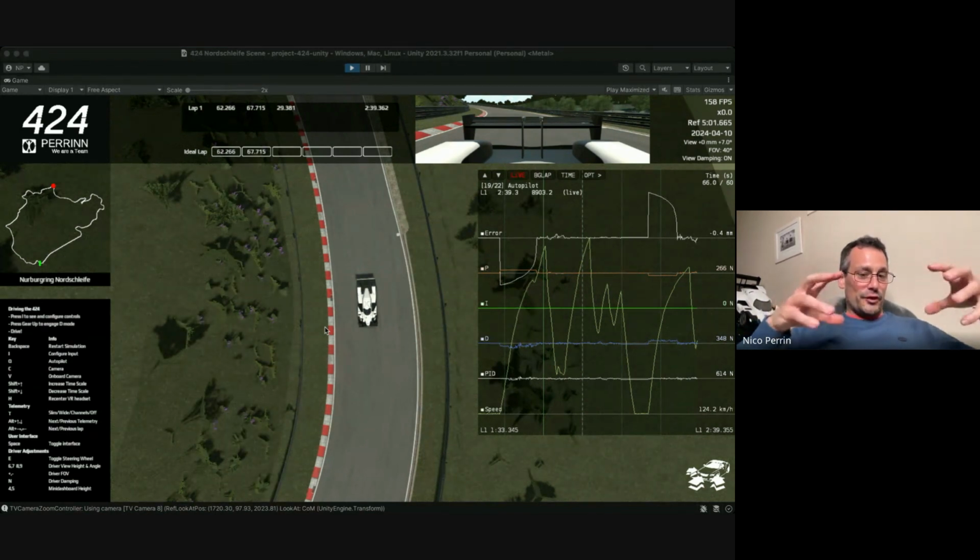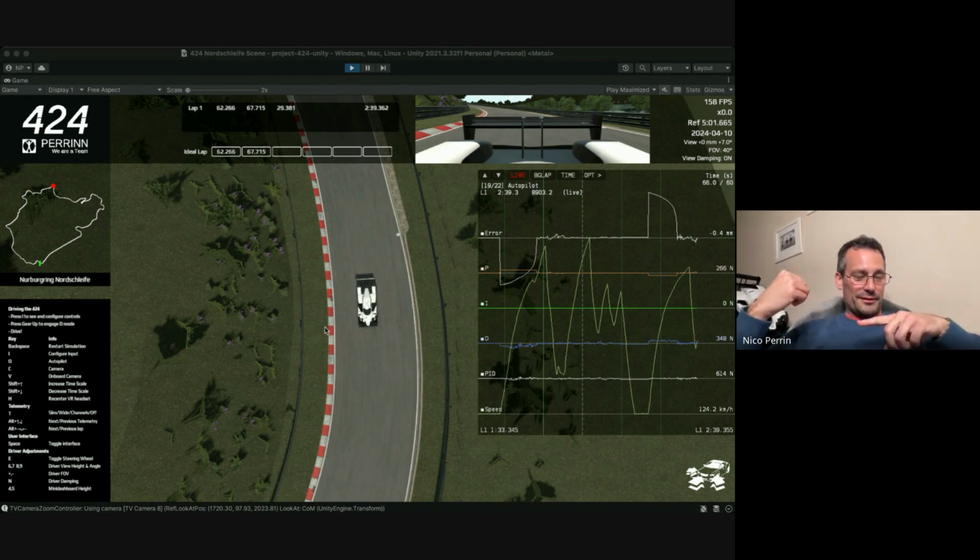Instead of being able to transfer some of the two motors' torque to the one wheel on one side, now one motor has to always drive the same wheel. It cannot apply some of its torque to the other wheel through the diff. So you're actually becoming limited by the torque. You're reducing the performance of the car. And it's also a double transmission system. It's heavier. It's like having two gearboxes. So I hope that answers your question.